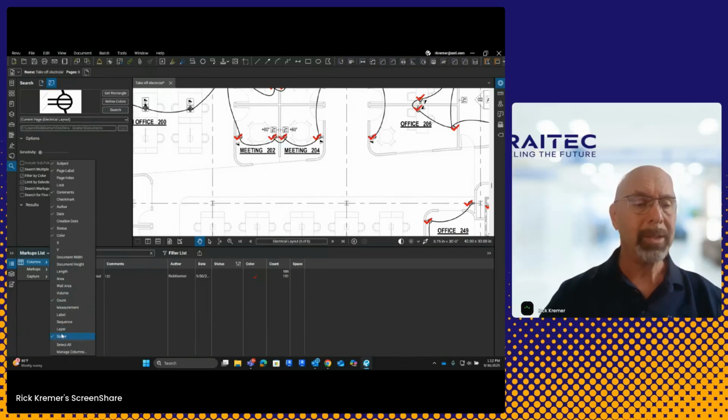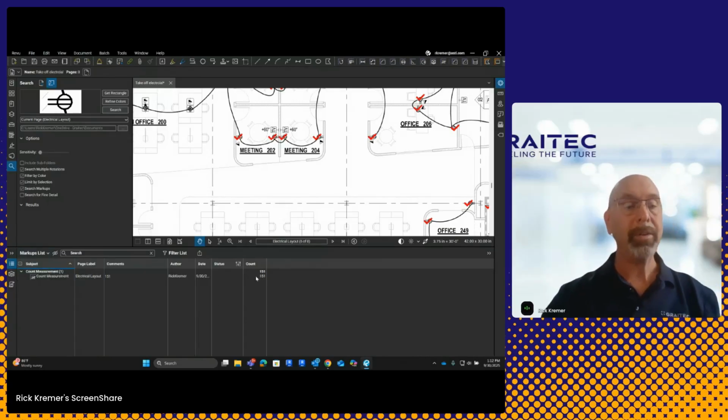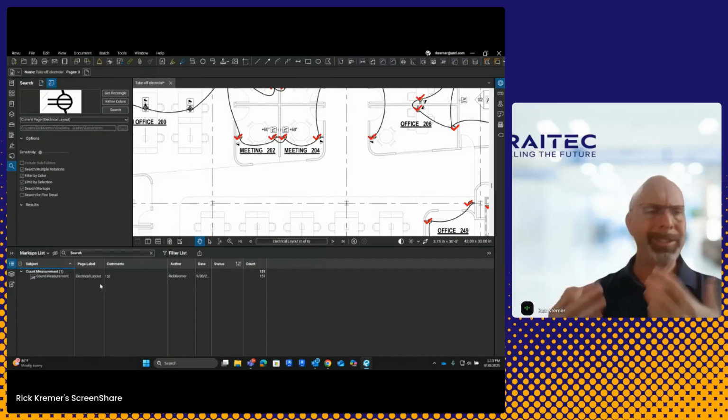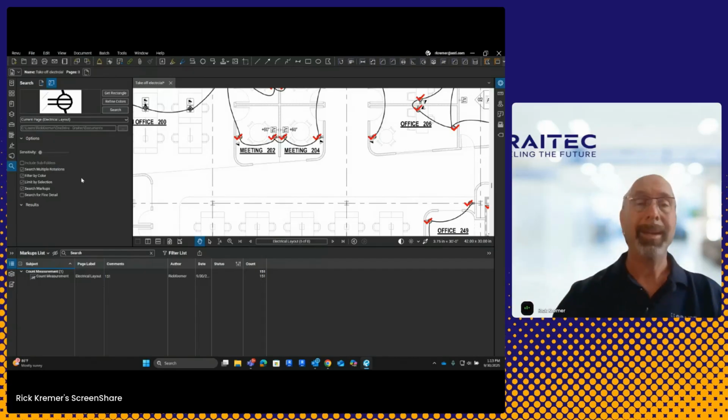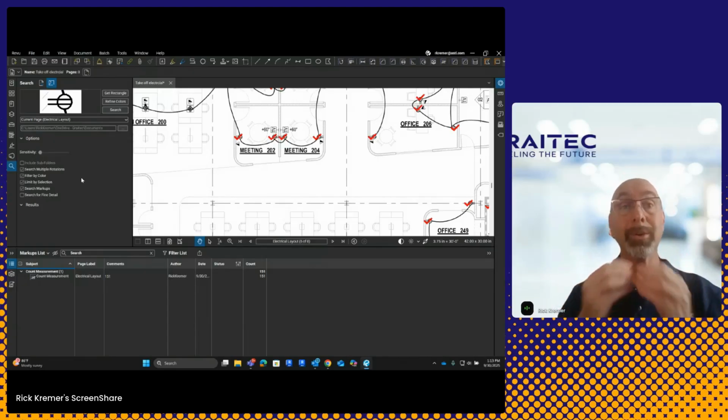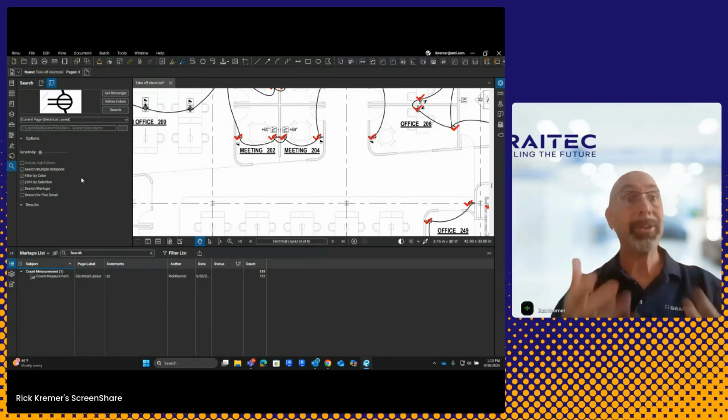Here, let's go ahead and turn off some of the things that I don't need, like color, and I'll leave everything else. So I have 151 of this object. But you're going to say, but wait a minute, it's just generically called count measurement. Here's where the fun begins. What we're going to do is now we're going to start to go through and tailor Bluebeam Review for our use as an electrical engineer.